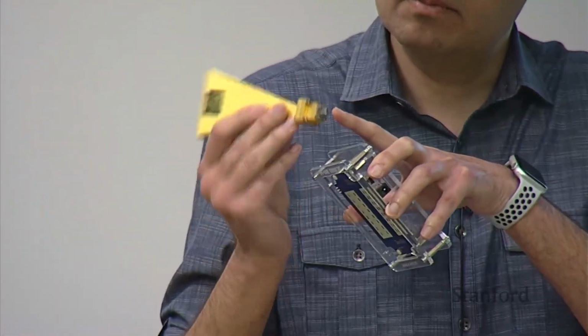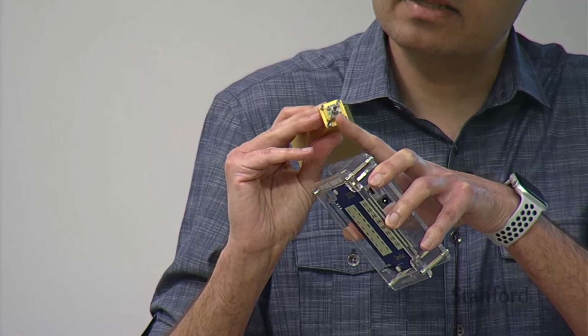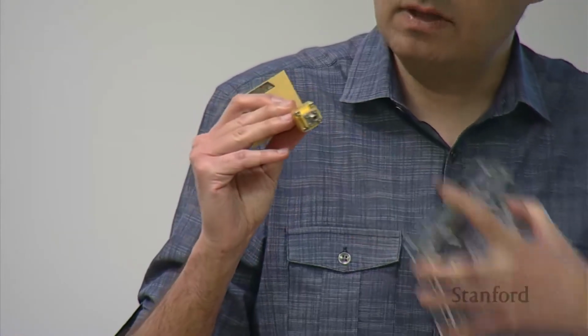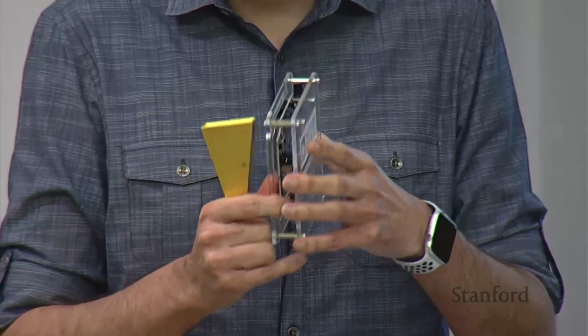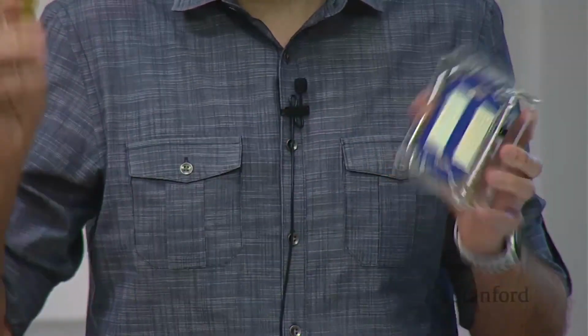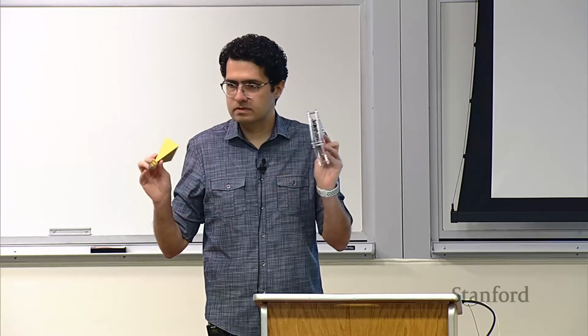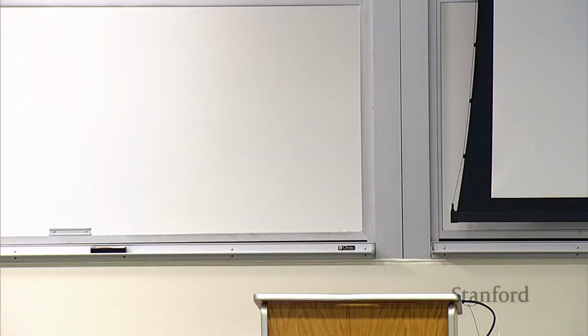It has basically a coax SMA cable feed, so you have to feed the signal to it. And it's just one antenna. This one has 6 antennas, 2 transmitters, 4 receivers, plus your entire circuit, and it takes a lot less volume than this guy. So that's why these are very desired for robotic applications. Anyone wants to see these? Pass them around if you want to see what they look like.